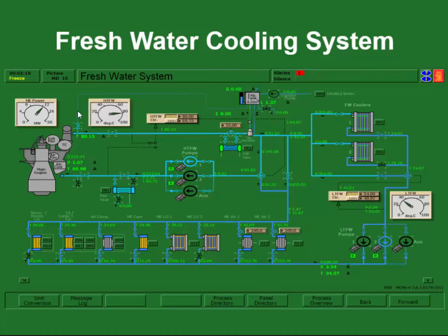So the next subject we'll talk about a little bit is the expansion tank and also the high point vents. This is a vent from the high point on the main engine. Typically these would come off one off each cover. The reason for a high point vent is to prevent the accumulation of air in high spots. Air pockets would impede heat transfer and could overheat the engine.